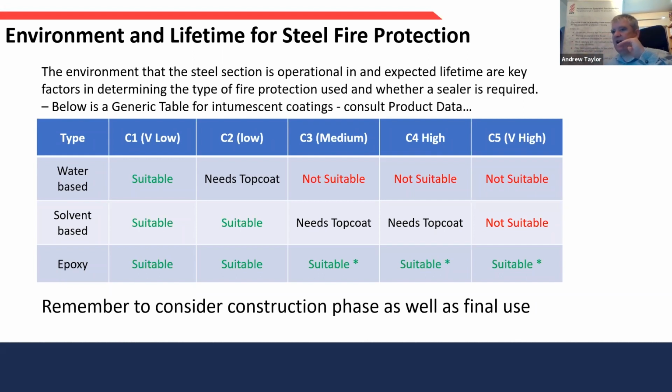But the thing I would mention here, which maybe is something we haven't mentioned before, is, remember to consider the construction phase as well as the final use phase, because the construction phase often is the most onerous thing. So you've got an office building that's going to be internal air conditioned for life of building, that's fine.